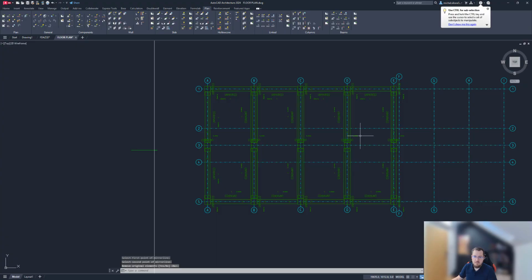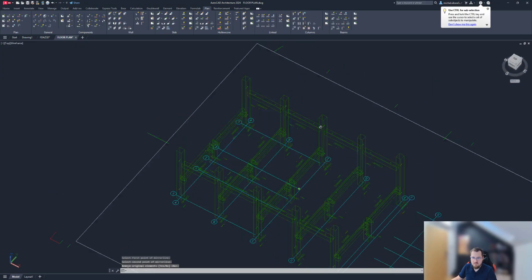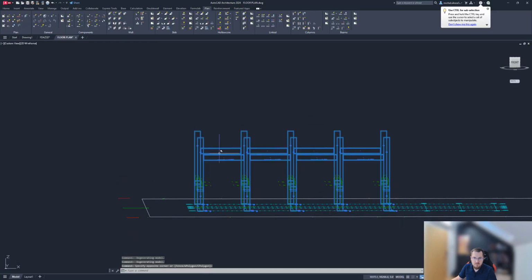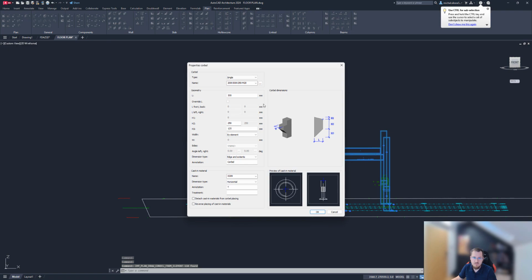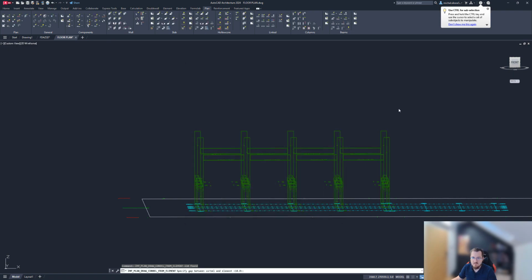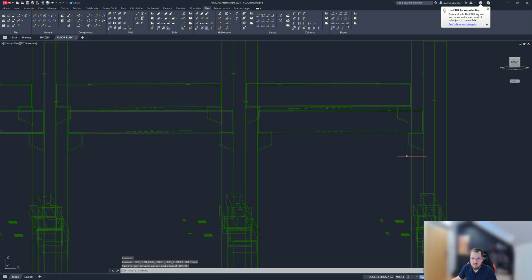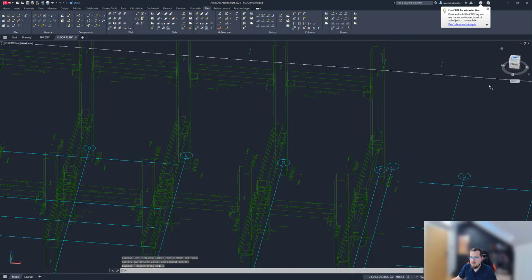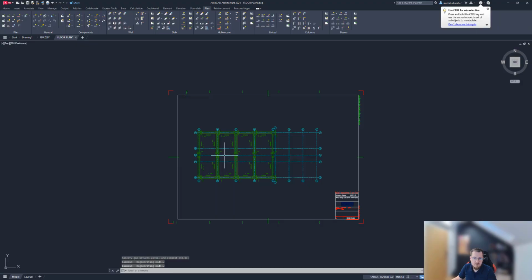You can see a couple of minutes, and basically almost the whole model is done. What I'm going to do, select those elements, and you can see the flexibility as well. I first selected the elements, now I'm going to add corbels. Impact still works, it still recognizes that, and the gap is going to be the same, and like that. Super quick, super easy, super convenient. Done. That's how we can do it.